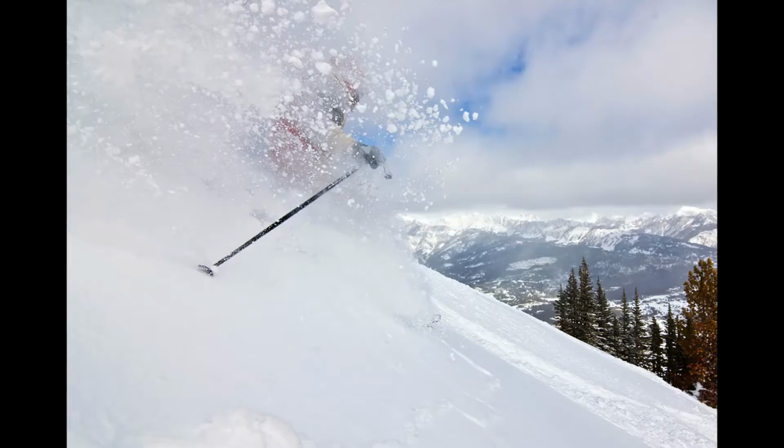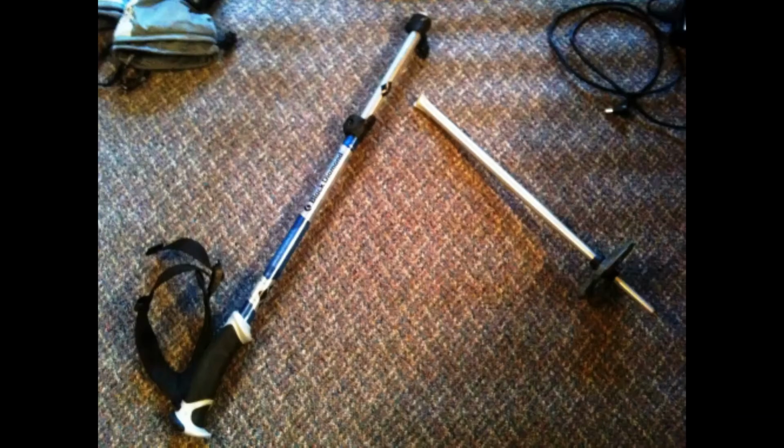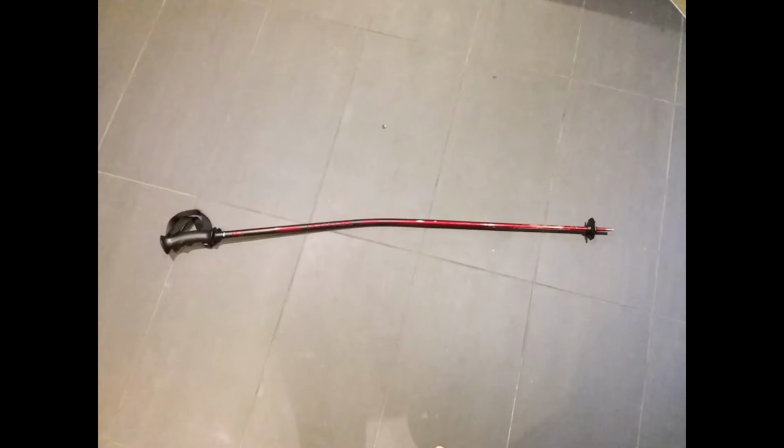Since we calculated a safety factor against static failure of 19.1 and over 200 billion cycles before fatigue failure, we wouldn't expect to ever see ski poles fail, but that is not the case. There are limitations to our results based on the assumptions we made. By modeling ski poles as thin-walled cylinders, we erase stress raisers at the handle and other locations from our consideration. Additionally, ski poles often bend or dent. These bends and dents could contribute to the overall state of stress, even though we were unable to consider them for this analysis.